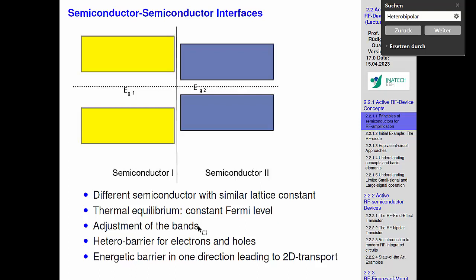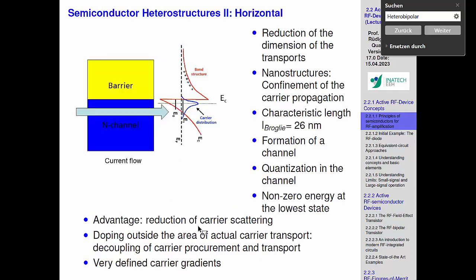The material with the smaller band gap will always be the faster one, where I want the conduction. That's something which we also learned. Smaller band gap means higher mobility. So I'm putting that on top, and if I do the right selection, then in the conduction band, the valence band will also follow, but in the conduction band there's a large band edge and a small band gap. Yeah?